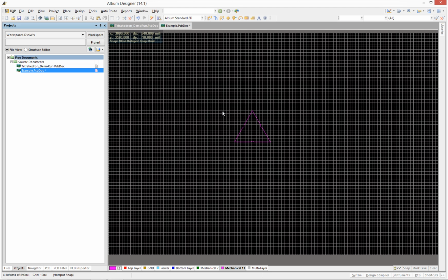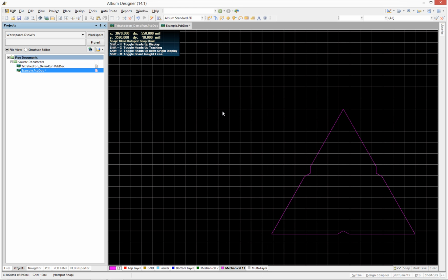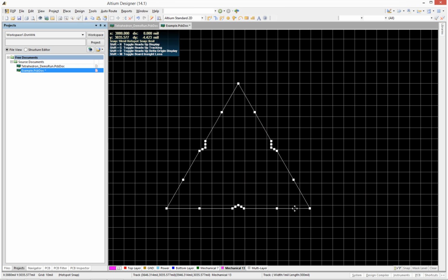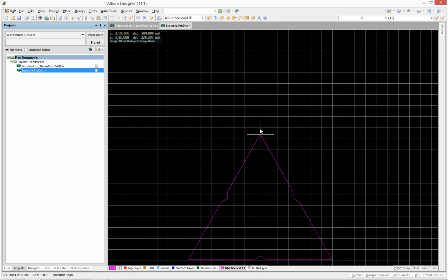Okay, and actually, let me jump up here. One thing that's very important is to make sure that this is on grid when it does get pasted down. Control Z. Let's do a Control Z again to remove it. And when we do a Control V, let's make sure we get this on grid. And the reason why it's important is because when we start putting the lines down to declare the sections, if those lines are not sitting on a grid, you'll get a crisscross, and those crisscrosses can result in additional regions that you weren't intending. So that's what we're going to try to avoid over here.